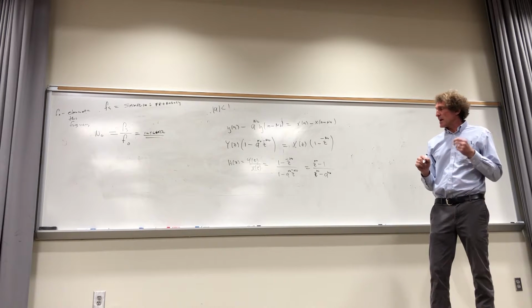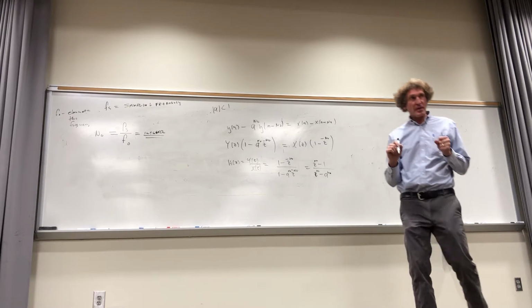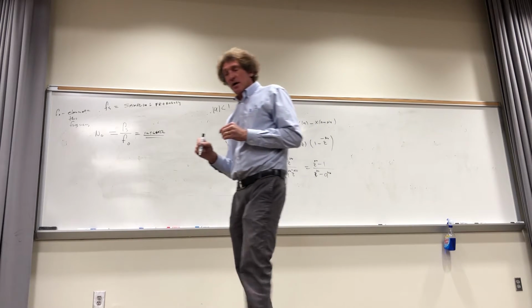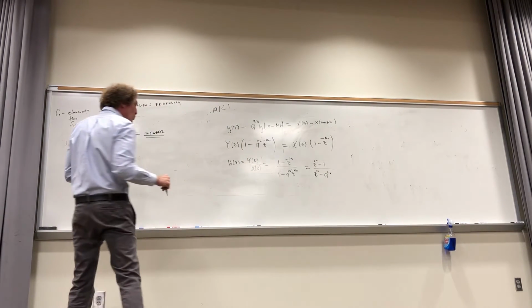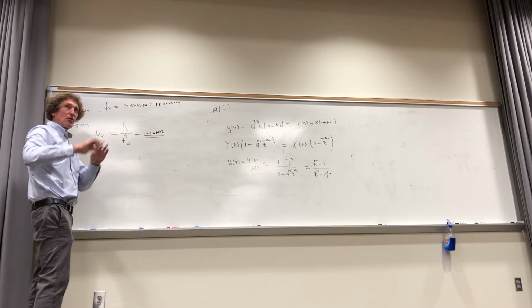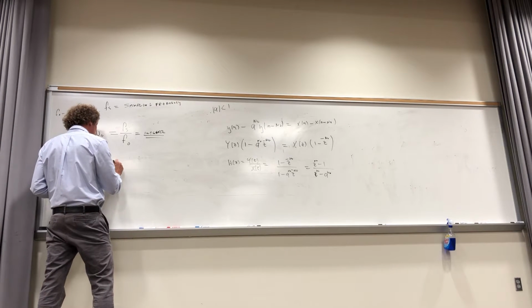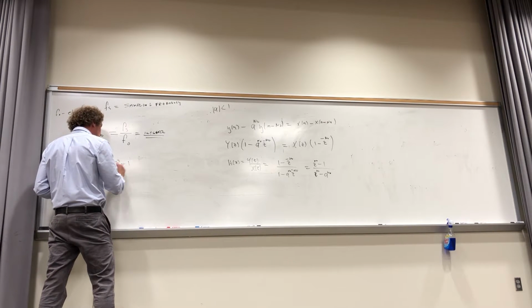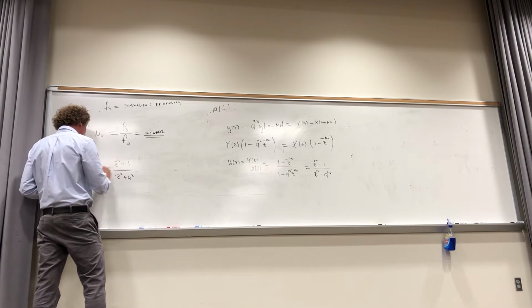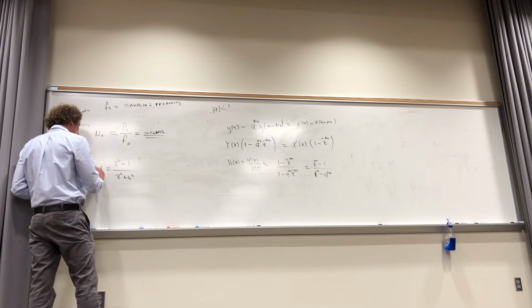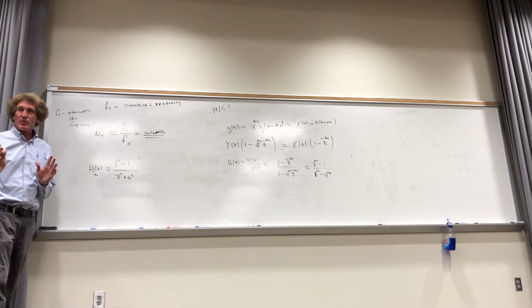I want you to think back just for a second before I keep moving on in there. The way we found out how come that other filter worked, the notch filter. If the cosine term wasn't there, we had really z squared plus 1 over z squared plus a squared was the h of z for the notch filter. Do y'all remember that? That's if the cosine went away.